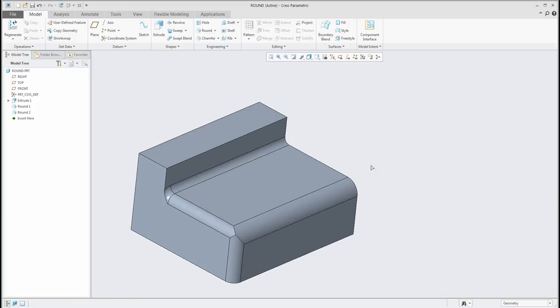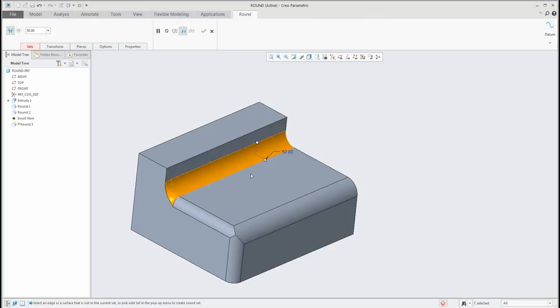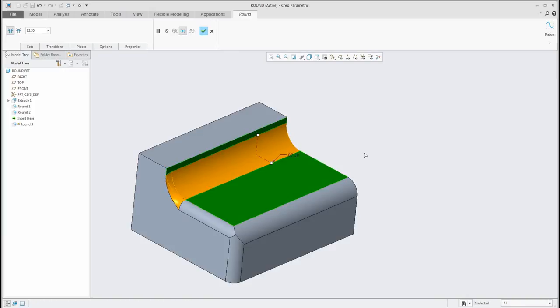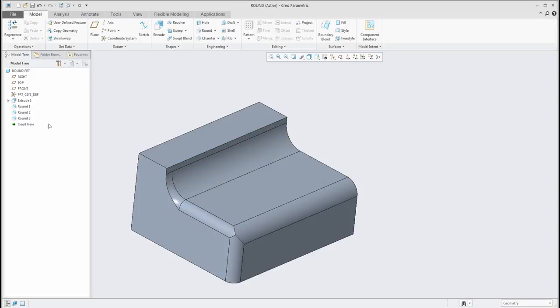Okay, sometimes you can create the small round feature, and then if you specify the round feature between two surfaces, you can create a bigger one. This kind of creation of the round feature is useful if you have problems with small surfaces and it's really hard to create the bigger radius. So it's something like a tip on how to modify and create rounds.